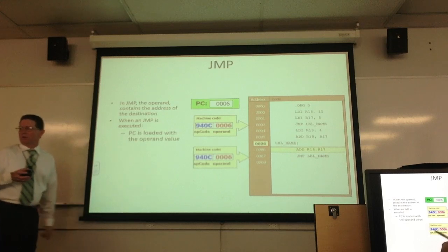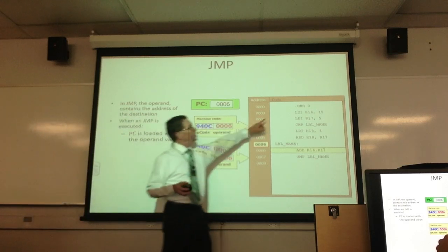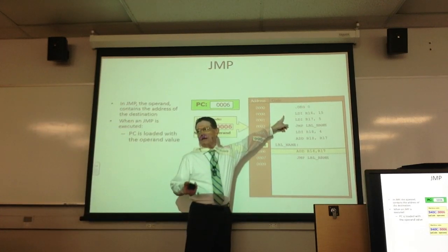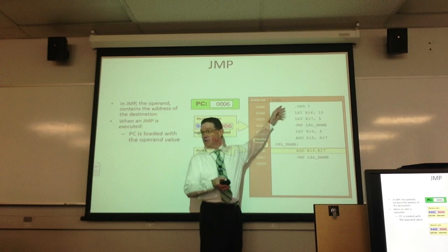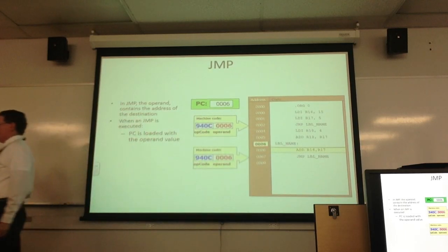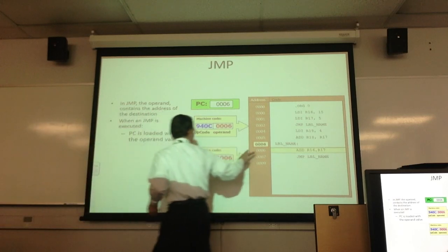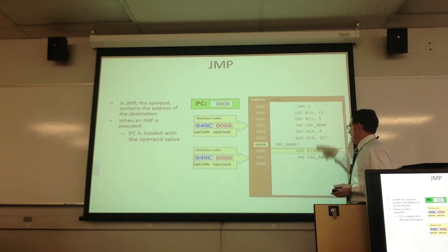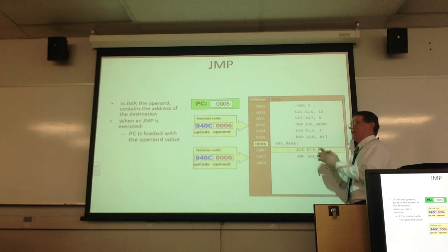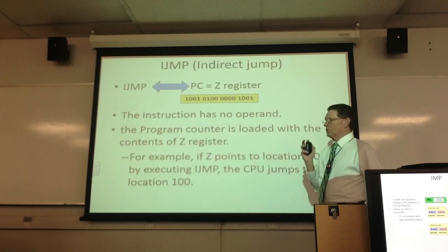Rachel? So if we wanted to exit the loop and just jump up to that LDI R18, for example, because it's there? Yeah, you would have added another label here. Oh, okay. Just add another label right there, and then you could have jumped to LBL_name1 and have LBL_name1 up here with a colon after it. Why would we want to skip those 2 lines? I'm only trying to demonstrate what is happening with the program counter and what's happening with the address. That's all. Yeah, it would make no sense, this will never get executed. Here I'm just going to have an infinite loop. But the idea here is what's happening with this and this, as far as where they're going. Okay, good question. No problem.